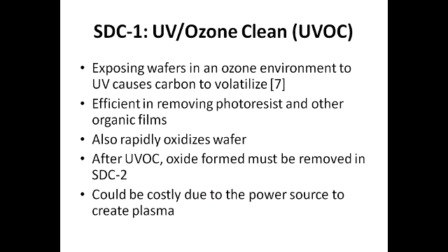SDC1 is UV ozone cleaning. Exposing wafers in an ozone environment to UV causes carbon to volatilize. Because photoresist is basically carbon, it can be removed. It's efficient in removing photoresist and other organic films.